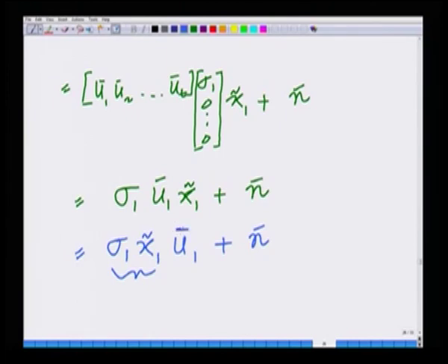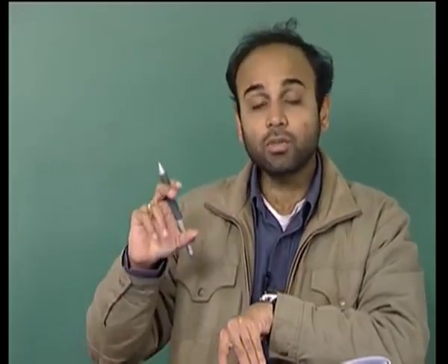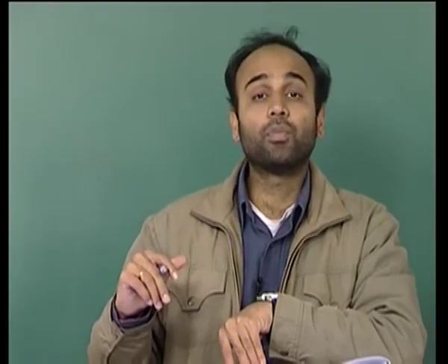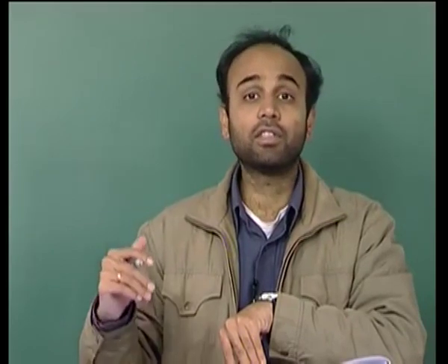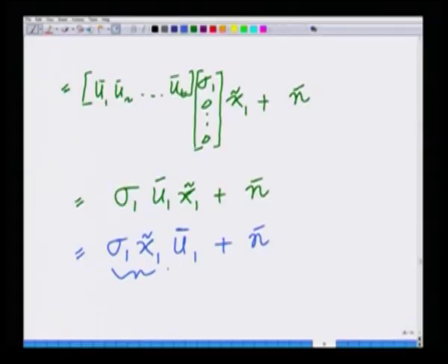So, this is now the scalar, and at the receiver u1 bar, not u1 tilde, u1 bar is the direction along which you are receiving. So, at the transmitter you are transmitting along this direction in abstract n dimensional space which is v1 bar, and corresponding to that you are receiving along the direction u1 bar at the receiver, which is the dominant receive direction.